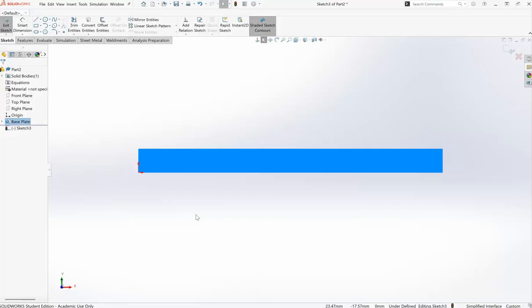If you look at the book and what it looks like, we're going to have two parallel vertical lines, and those two lines are going to be connected with a semicircle. And the command that we're going to use is tangent arc, which means the arc is going to be tangent or connected to those vertical lines. SolidWorks has kind of a shortcut where we're going to remain in the line mode, but then there's a way to go into tangent arc and then back out into the line mode.